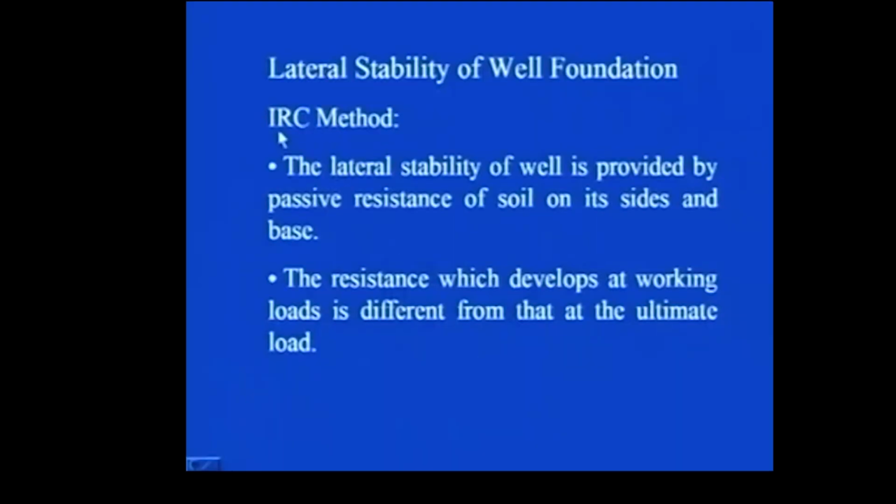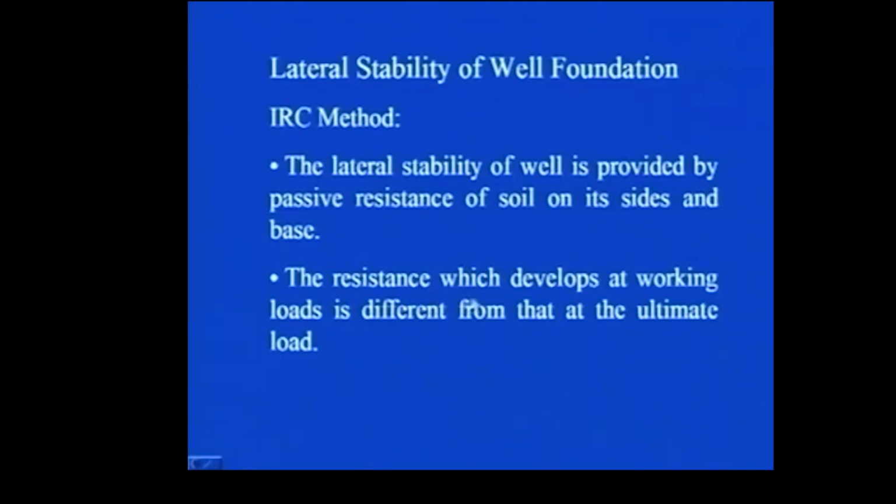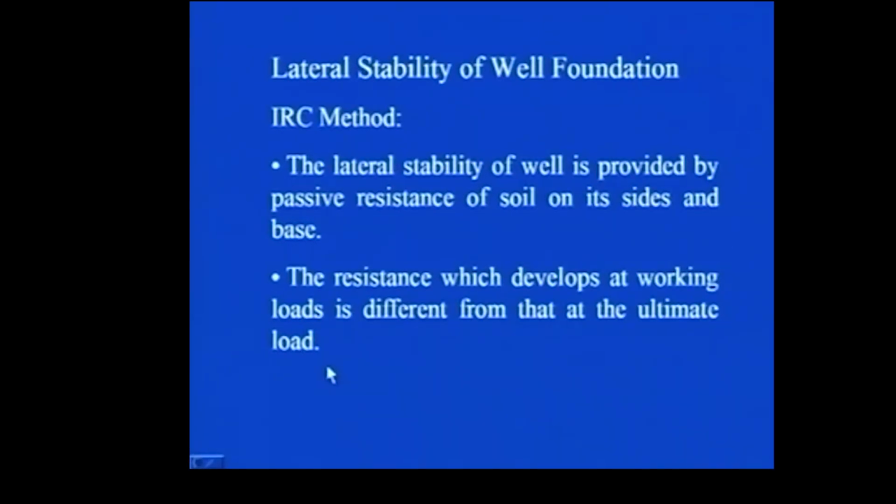First, I will be discussing some of the general aspects, and then we will see what the recommendation by IRC is as far as the elastic theory method is concerned. In IRC it says that the lateral stability of well is provided by passive resistance of soil on its sides and base. The resistance which develops at working loads is different from that at the ultimate load. That is so obvious, and it has been associated in the recommendation by IRC also.